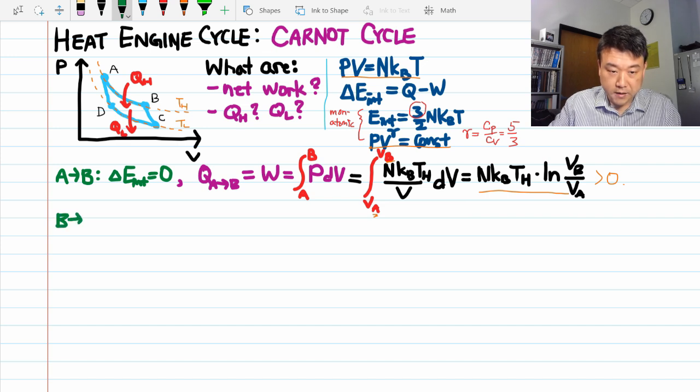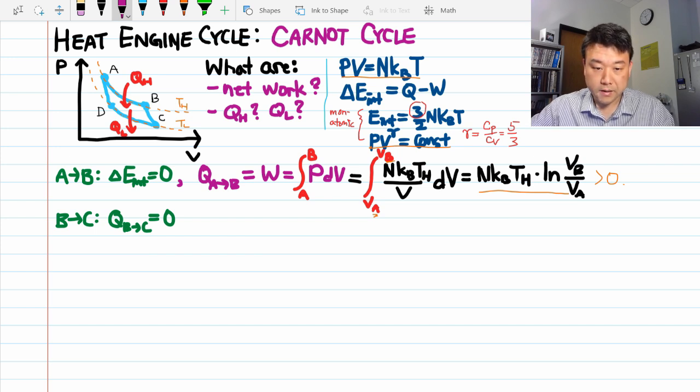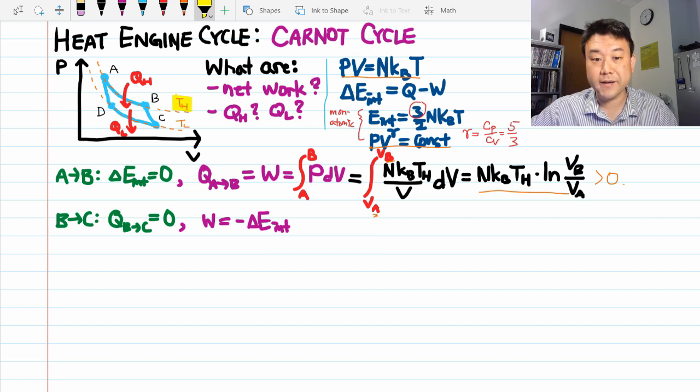This is new. It's an adiabatic process, and that means by definition, heat transferred during this process is 0. Alright, so that's interesting. Let's look at the first law of thermodynamics. So Q being 0 means that the work done is minus the change in internal energy. And because we are given the temperatures, or at least I'm pretending they're given, it'll turn out that that's actually a quicker way to calculate work than to try to calculate work by using the definition of work. So we're going to do that.